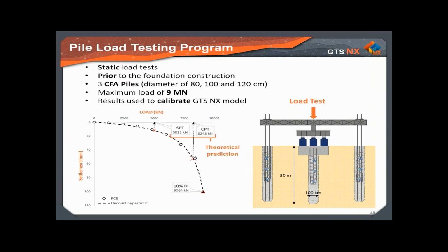On the next slide, I will show you some results of pile capacity prediction based on the cone penetration test. So here we are heading to the pile load testing program. The static pile load test, just to define, is composed of a real scale pile which is tested by applying load, and at the same time the settlements are recorded for each load step, and the figure on the right shows the test scheme, which is basically composed of the test pile and the reaction piles.